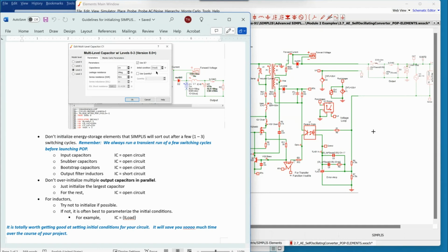I would like to add two comments on the initial condition. When you say bootstrap capacitor, which kind of bootstrap are you talking about? Okay, what I'm talking about, and I don't have a good scope, is when in a sync buck you have a bootstrap capacitor for the high side FET, providing a bias for the high side FET. Right. Okay. Yeah.